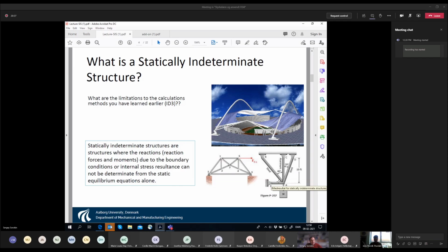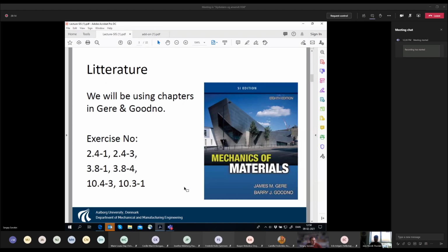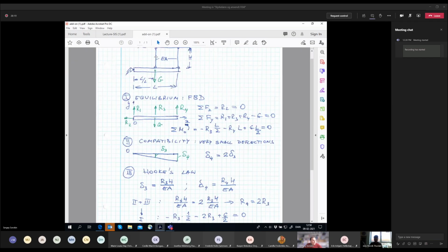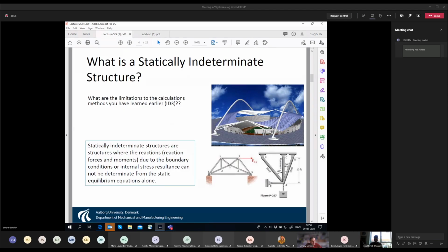And then this will give you exactly the requested number of compatibility conditions. So in this case we have 2 elements and 1 compatibility condition. And in the case which I have shown from the slides here, we have compatibility between displacement of this point. This point belongs to this rod, this rod, this rod, and this rod. And they're connected before, and they are connected after.